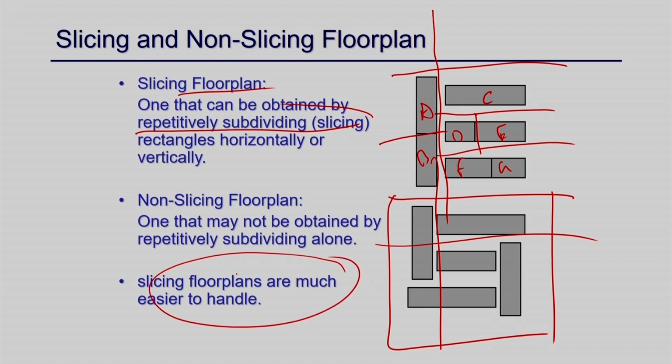Such a way you make the connection so that you can make a sliceable floor plan, and we will see that it is actually helpful, in that this sliceable floor plan is easy to handle for placement, routing, and all other components. So usually the kind of floor plan we try to generate is sliceable, right? What is sliceable? I just repeat again: something where we can bipartition each sub-component at a time to generate your layout plan, right? So this is how you can do it, in any order, horizontally or vertically. Okay. So these are some terminology that you should be aware of during floor planning.